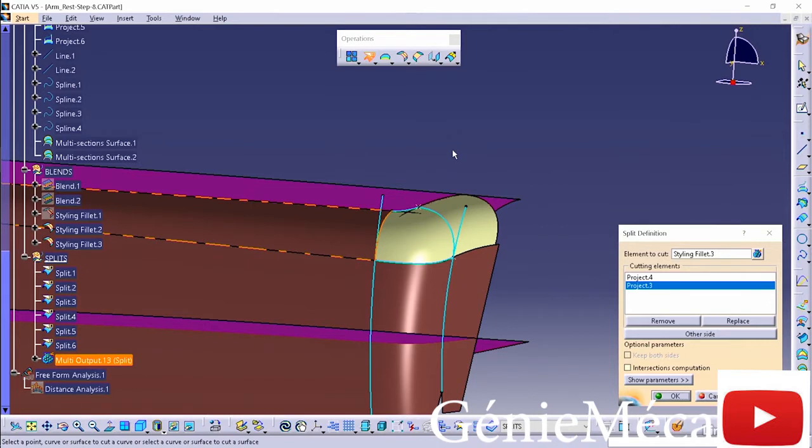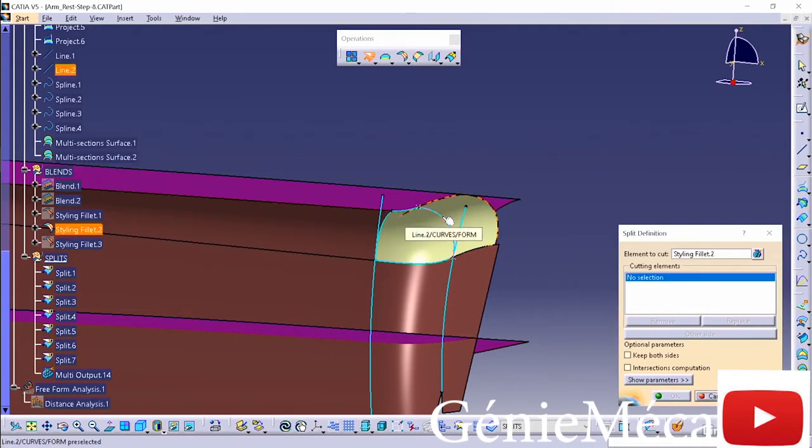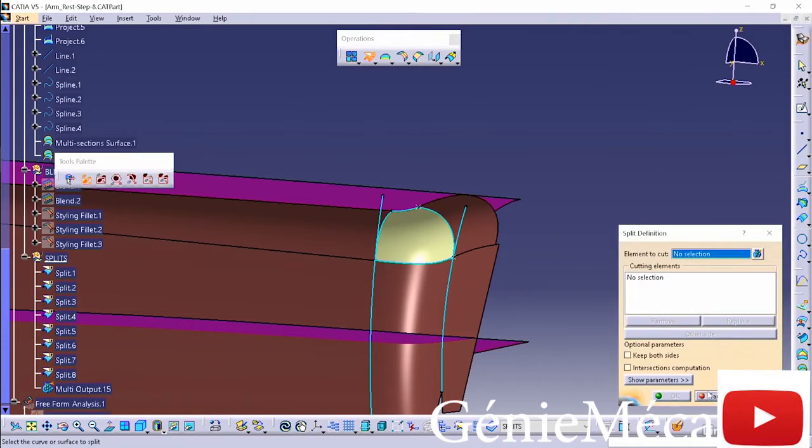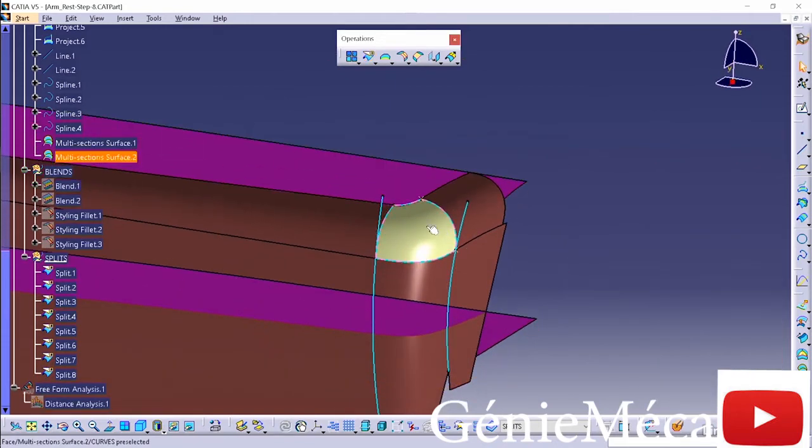Little tip is when you're splitting things, it's kind of hard to see sometimes what's being split if you don't change colors. So that's why I have that extra geometrical set in here with the graphics change. So as you are doing your splits, it automatically just changes those colors so you can really graphically see what's happening. And you'll know what's split and what isn't split. These tertiary corners do not need to be split because they were built to that mesh which fully encapsulated them.